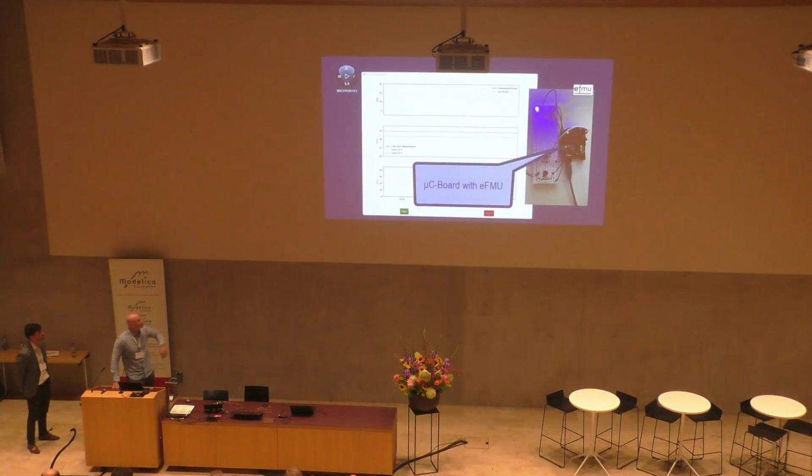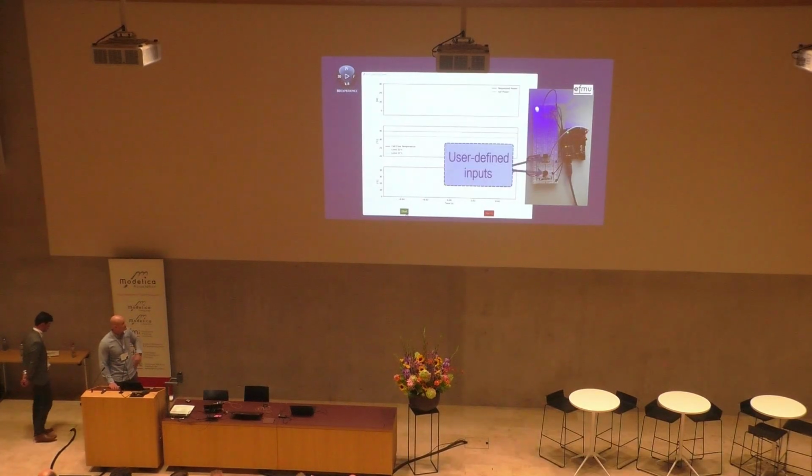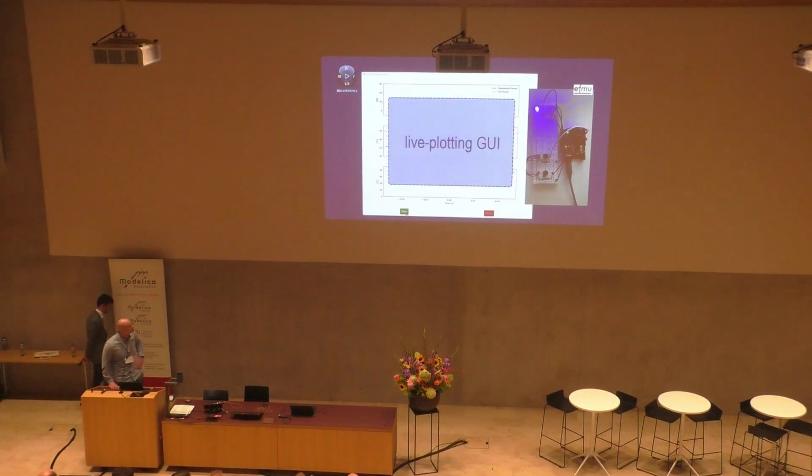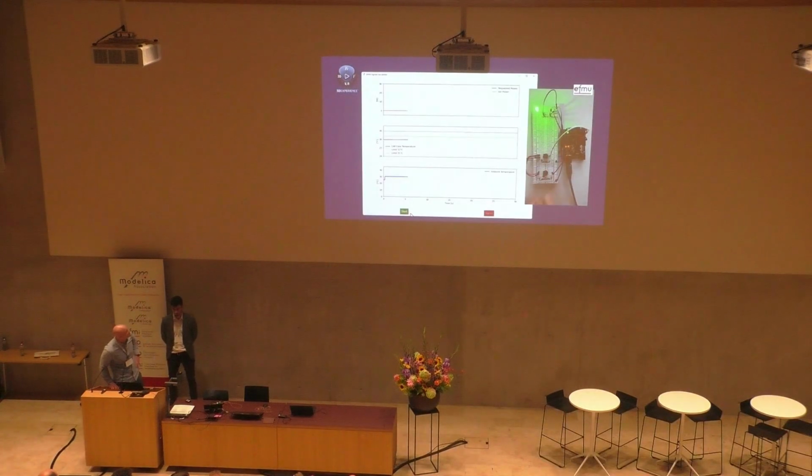Okay, so this is a Python UI to better see the real signals that come in and are computed by the EFMU. See on top the status LED, and then if you start, you see now everything is fine. The green line in the middle plot, when we hit it, then it starts derating, and the purple line in the middle plot will then be the maximum limit and will completely lower the power that we can request. So we see here, we start in the power limitation phase.